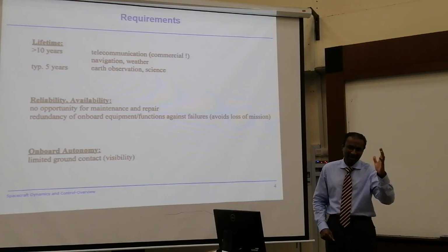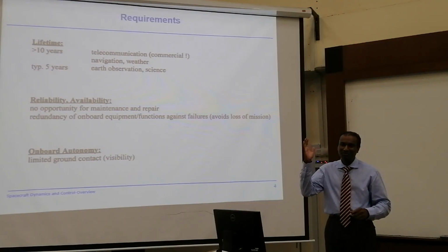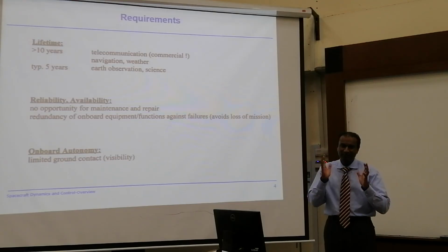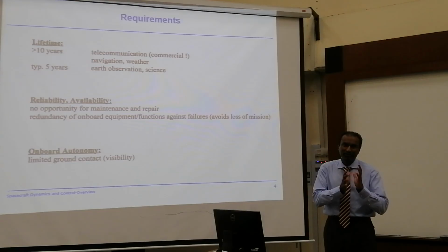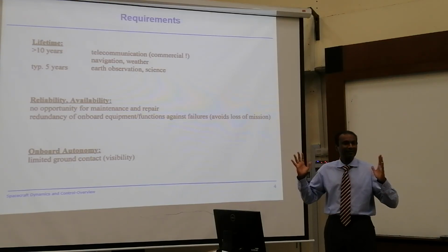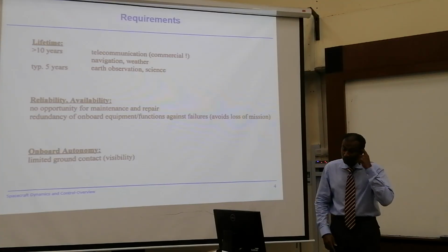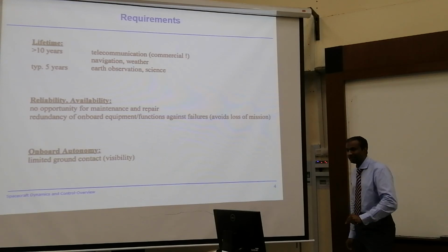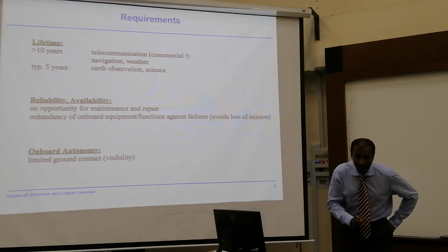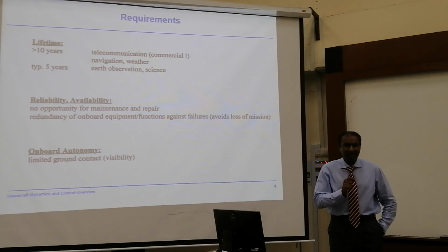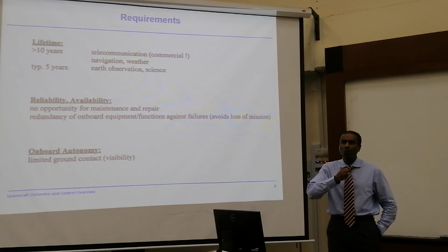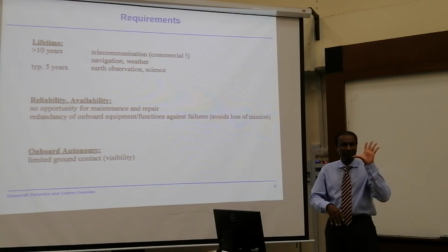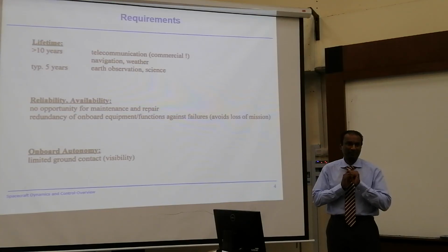Let's say a satellite has 5 systems, and you want to make sure every one has a backup. That means if my battery fails, I have one backup. So you will have another satellite in here. Might as well just separate this. So you don't do hardware redundancy, you only do software redundancy. But in a very, very critical system, you may compromise to do 1 out of the 5, you may have 1 redundant. Yes, that's possible.